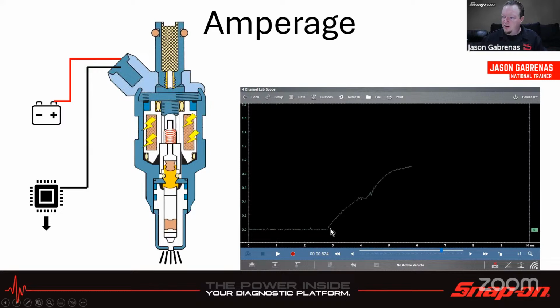So amperage is going to increase. You want to see a nice smooth ramp go up. In this case, we have a little bump right there. That little bump is the point where that pintle actually leaves the seat and starts spraying fuel, because there'll be a little bit less resistance at that point.